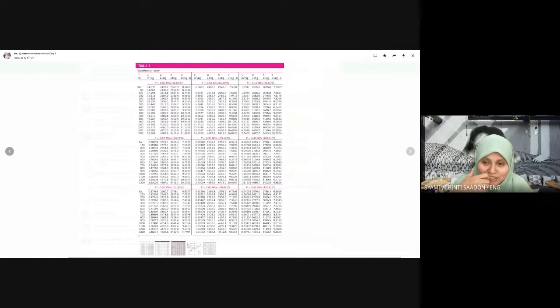Oh, okay. What we had to calculate was H2. We have to calculate H2, H final, using the energy balance equation. And we use the table. By using the table, we no longer need to calculate temperature. We just read the table, read the temperature in this box, because the pressure is 300 kilopascal or 0.3 megapascal.